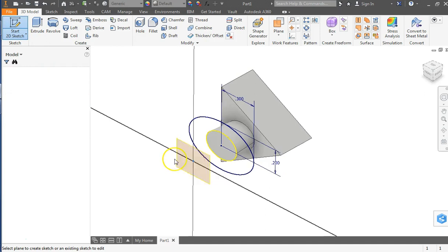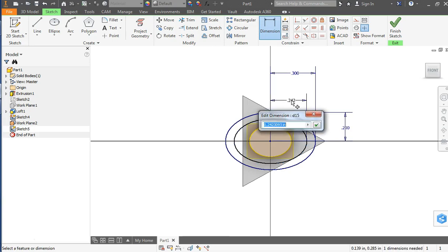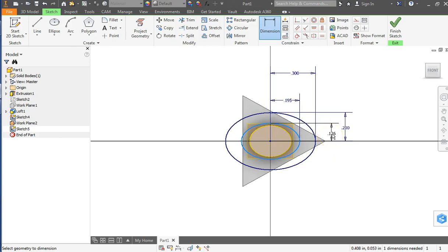We'll start a sketch here. This ellipse is going to be the waist. Still, the major and the minor is going in the same directions. It is going to be narrower. So we'll dimension. And let's see. What did I jot down? I measured that and agreed with them close enough. So their dimension going all the way across was 0.39. So halfway is going to be 0.195. In the minor direction, they have 0.31. So half of that is 0.155.